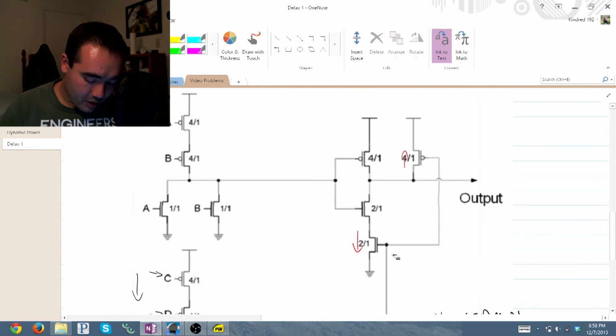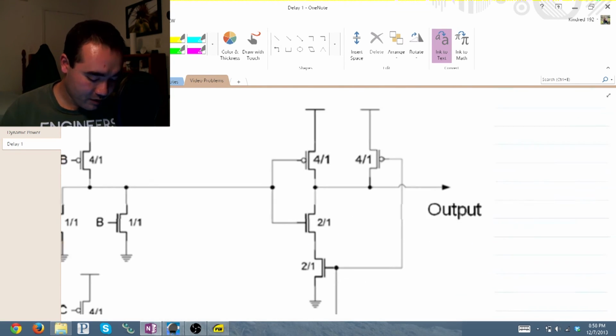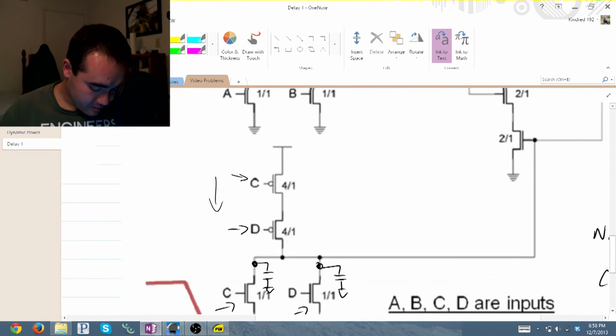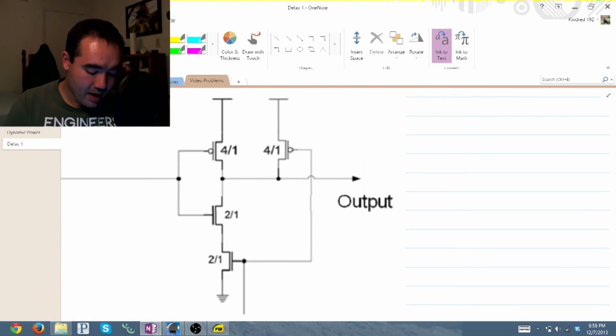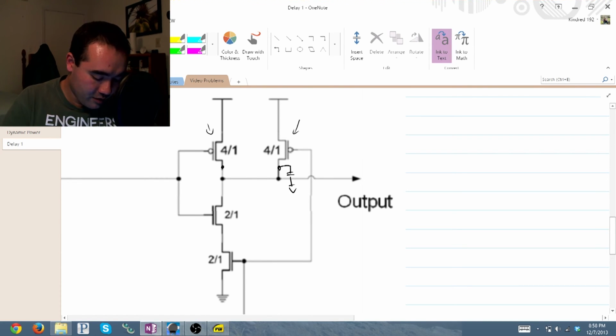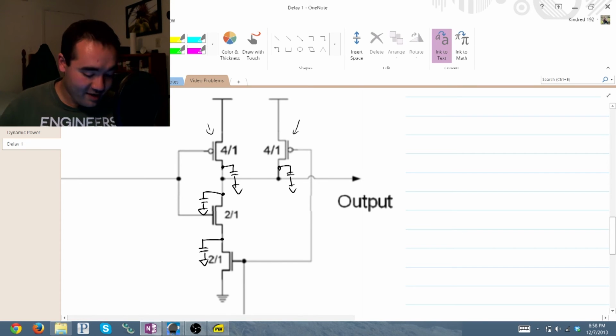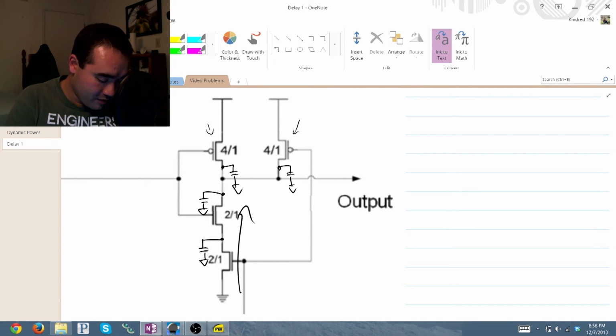Now, we'll move through this one a little bit more quickly because we're more familiar with how this works now, I would expect. So, we have these two PMOS transistors. They're both going to VDD. So our equivalent capacitances are right here because these are the closest to the output. We have an equivalent capacitance right here, closest to the output. Same here. Now, our path of propagation is through here. Therefore, our resistors go right there.